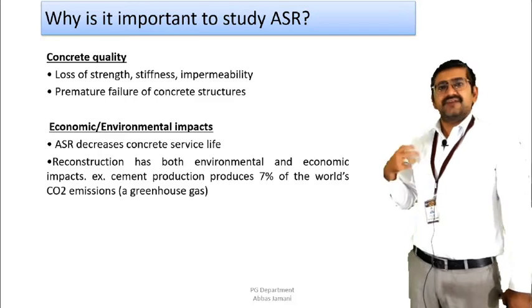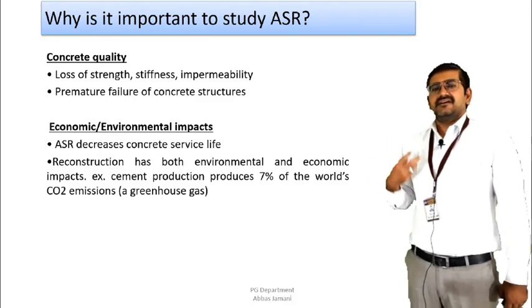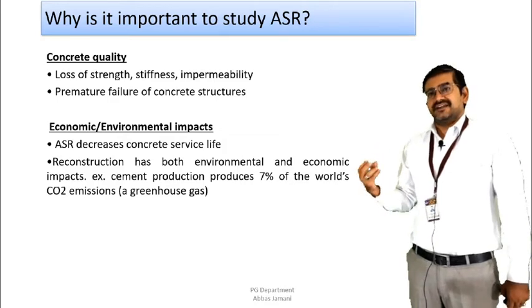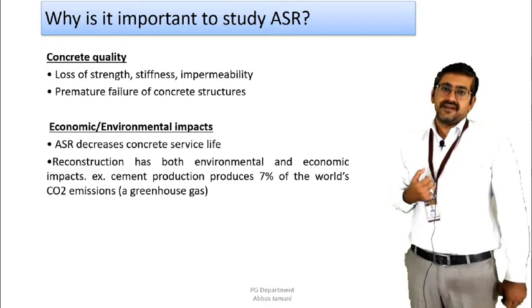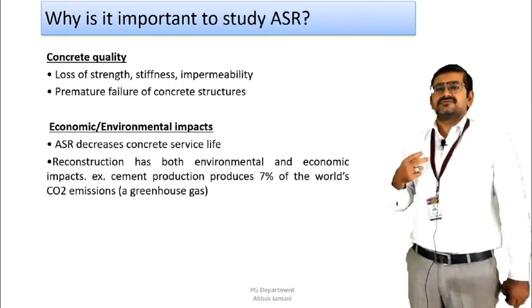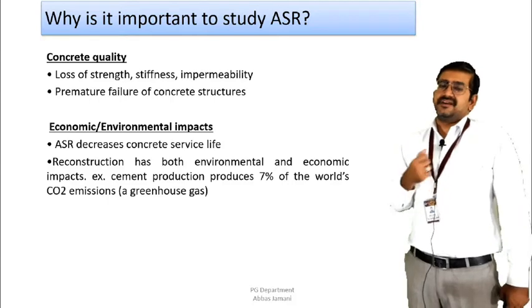And at the same time, due to this external pressure that is generated, the cracking and spalling takes place, and as a result, premature failure of concrete is likely, right? So that is why it is important for us to understand this process very clearly so that we can avoid these types of failures in the structure.